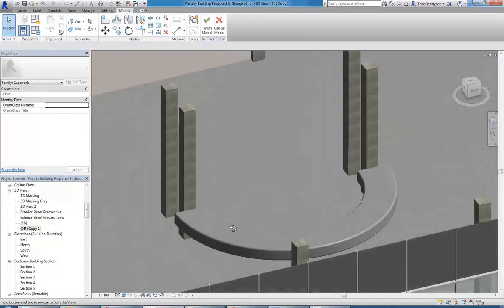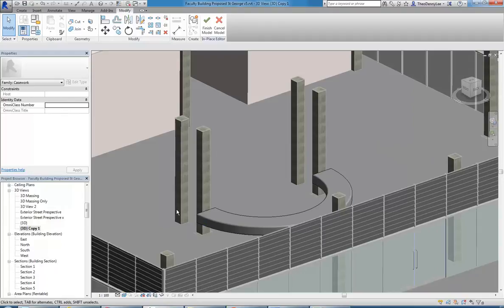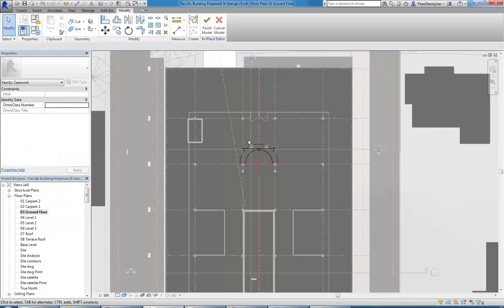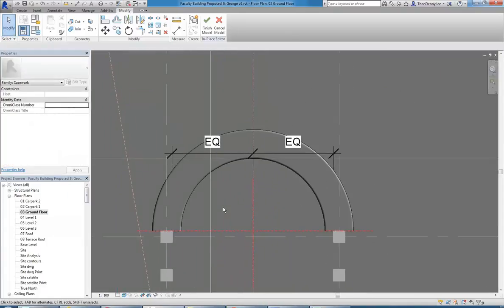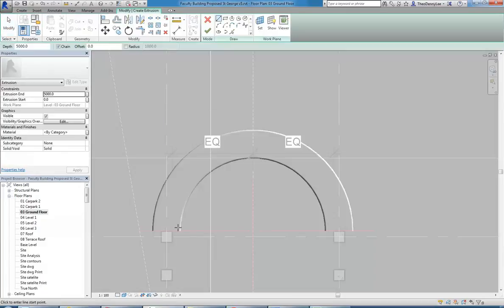To do a set of cupboards underneath, I could do another revolve, but maybe just so it's clear, I'll show you could easily make an extrusion for that. So if I go back to create and then extrusion, I can use an arc with centre ends arc.